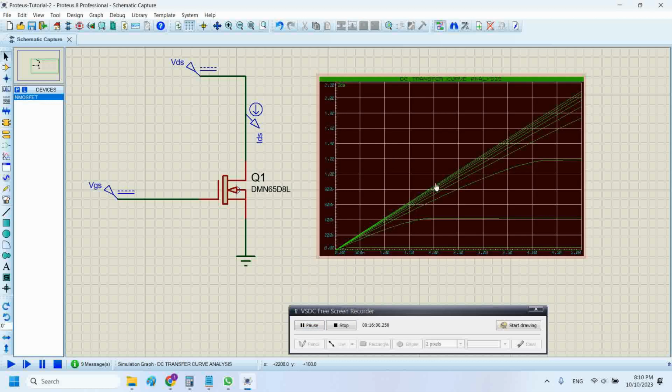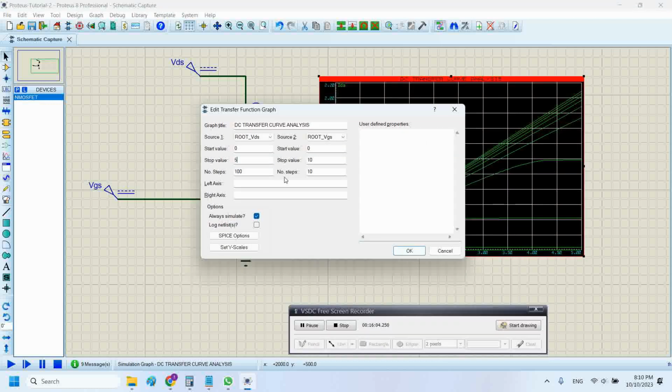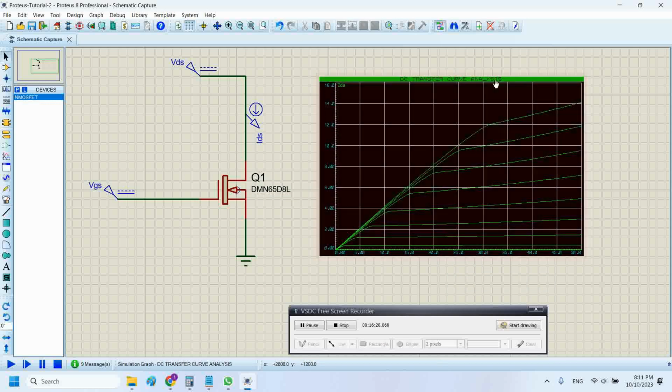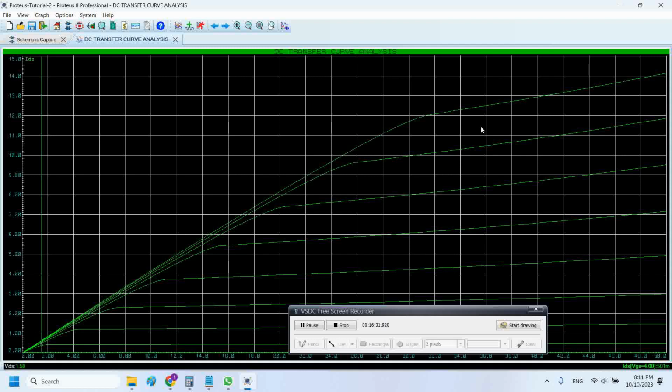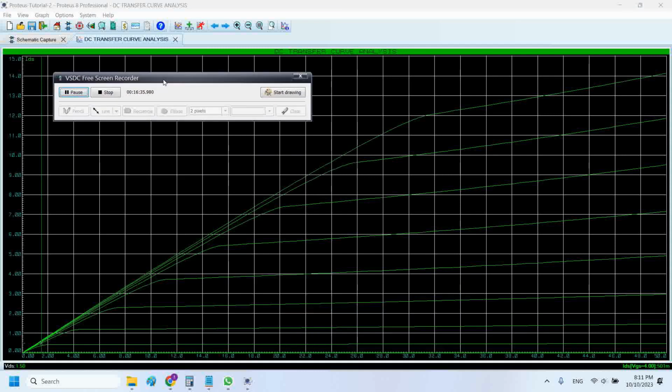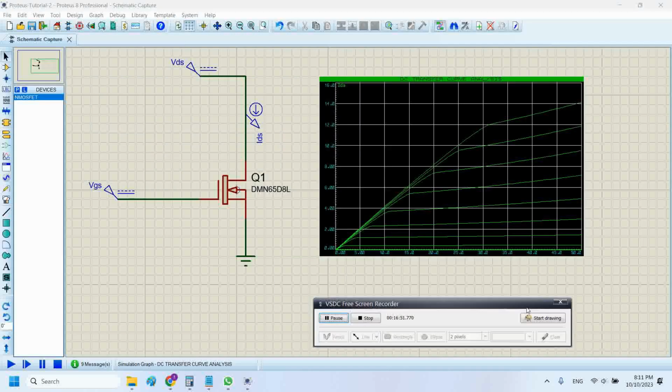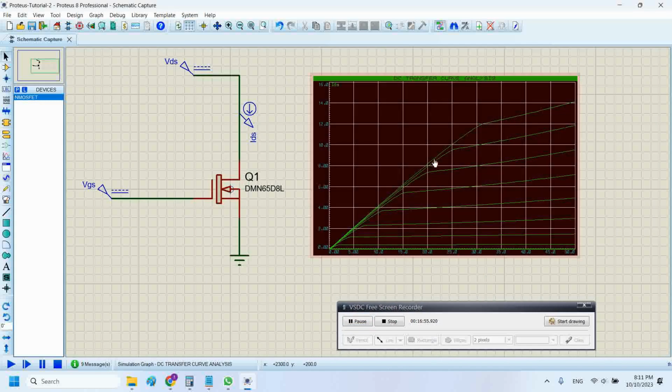And also we can increase our sweep value, say we want to sweep VDS to 50 volt, and we can increase our number of steps to like 200, which would be a bit less, like 1000, and we resimulate, and we can see here, this is the graph you might be looking for. See, this is a typical transistor characteristic curve which you might be interested in seeing. On the left scale you can see no microampere current flowing. This is a real practical simulation of the transistor characteristic.